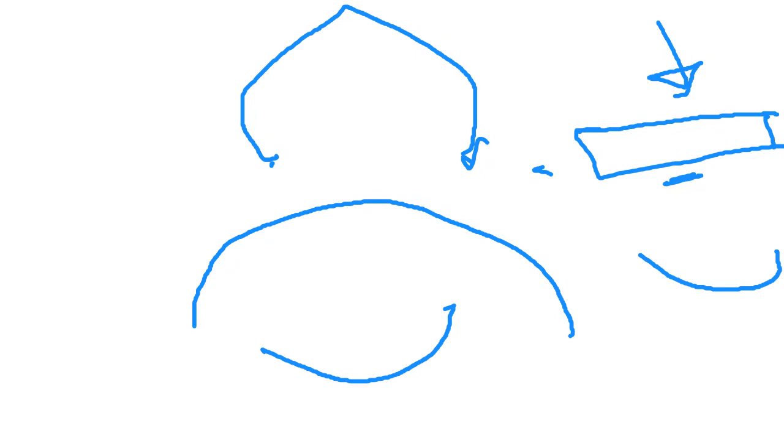I want to change the color so that you can understand. So if you try to reverse this diagram and then apply the load, then this entire system will be in compression, right? Or your bottom portion will never be in tension. That is the beauty of precast beams and precast slabs, etc. We try to make a shape of that beam in a manner that once we apply the force, the tension should not be there, or there should be a minimum tension which should not induce cracks in the structures. Are you able to understand this?